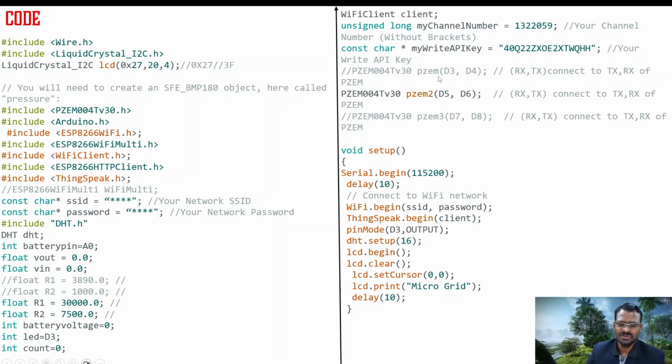And as I told you a little earlier, in case you want a separate relay system for different types of loads and separate energy monitoring sensors, we can have 3 different energy sensors, which I have shown here. This is for one, this second, and this third one. All of them use soft serial. Based upon the requirement, you can use 1, 2 or 3, even 4 energy sensors can be connected. Since it is not hardware serial, it is only software serial, we can connect them to any digital pins, even on an Arduino Uno or whatever Arduino you are using.